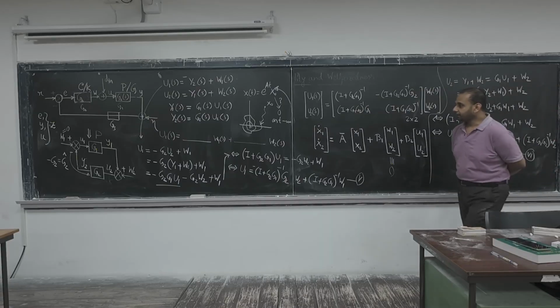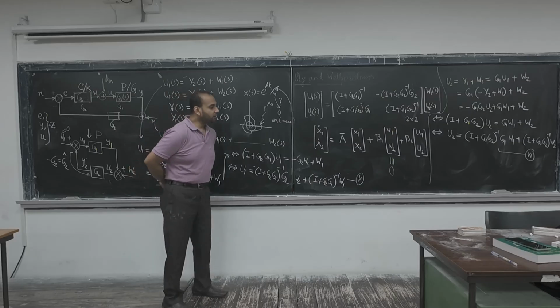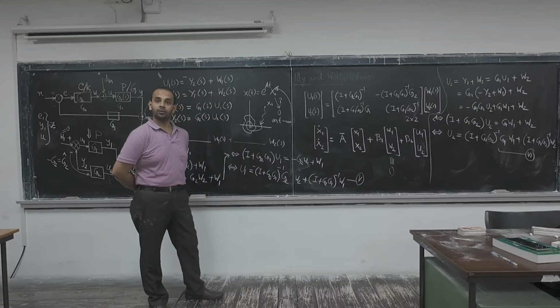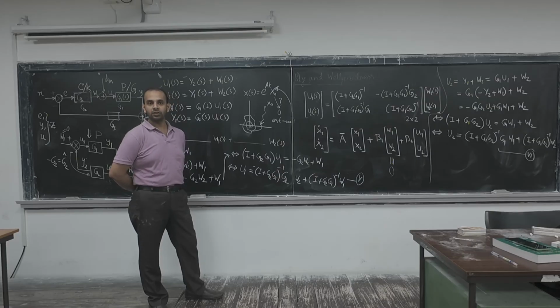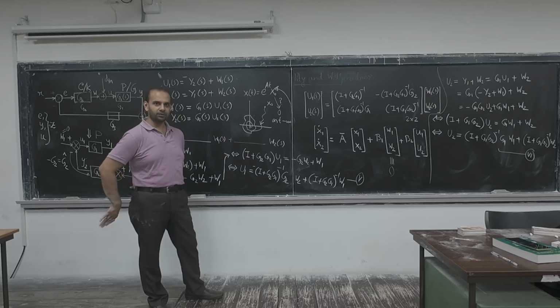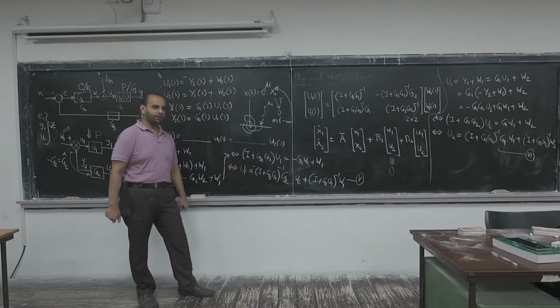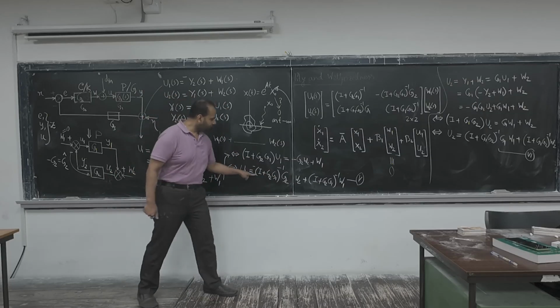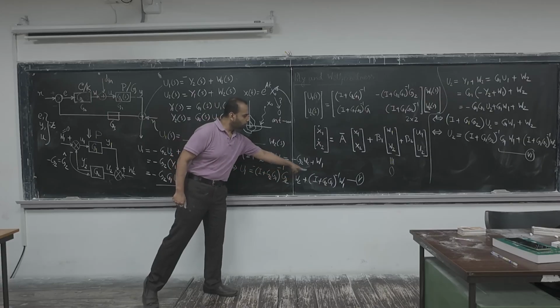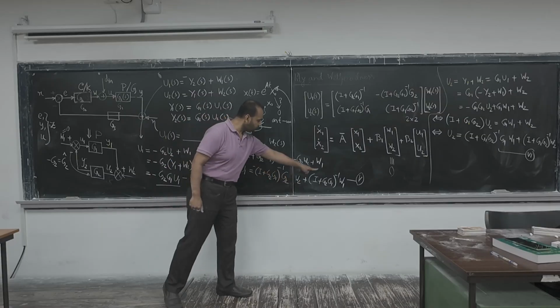And now there is one last thing, which is well-posedness. Well-posedness, last day, what did I explain? That is whether the signal exists, right? In the time domain, whether you get a unique solution to the differential equation of the closed loop system, right? I explained with respect to the differential equation. Now in the frequency domain, what will happen? You see my U1 is this entire thing times U2 plus this entire thing times W1. Okay, so this is W2, this is W1.